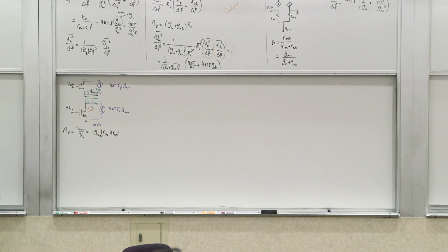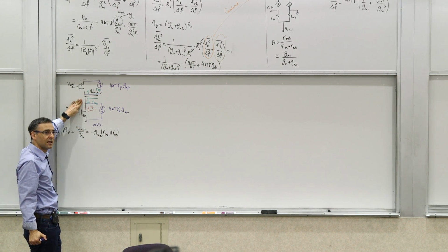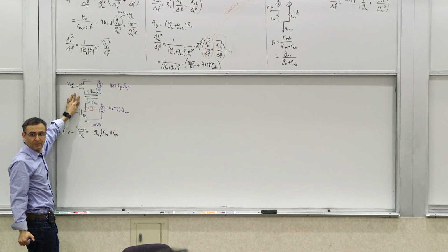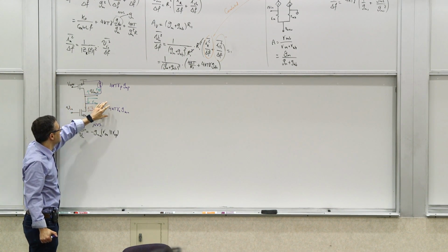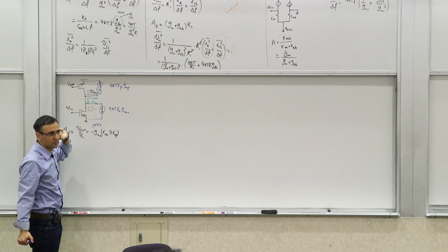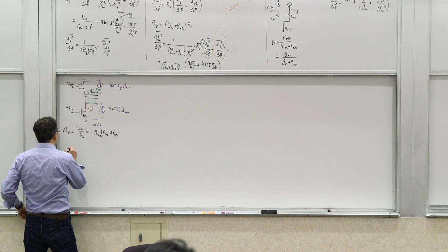We can always use the full procedure, which is to convert to the output voltage. What is the output resistance here? How does this current convert to output voltage? Through the resistor RON parallel ROP, right? That's the total resistance on this node. So it's this thing times RON parallel ROP plus this thing times RON parallel ROP. Let's write it that way.